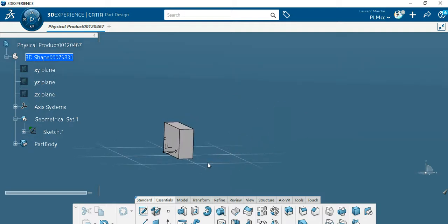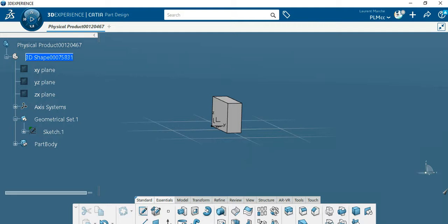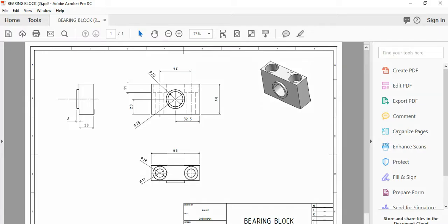You got different steps to design the holes here. Take care, we got different diameters and different dimensions here. 11 for the big one and through hole for the small one, diameter 11. Then we will design the cylinder outside. Okay, the big one, diameter 25 with a width of 3 millimeter. And at the end, the last step will be a cylinder inside of 20 millimeter diameter.